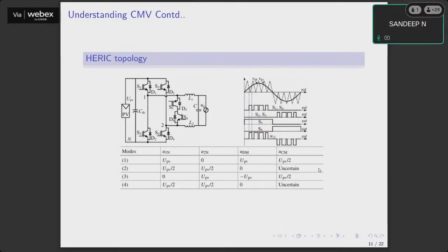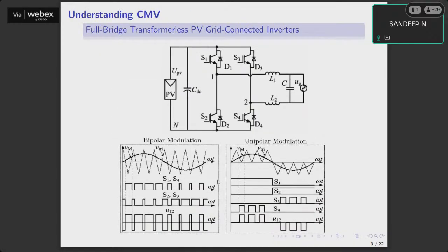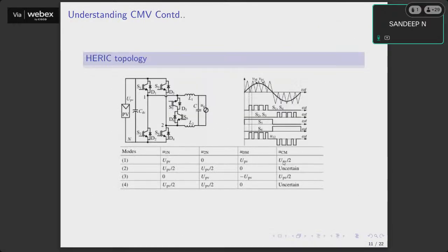So out of these two, unipolar and bipolar, unipolar is better because harmonics are less. The moment harmonics are less, the filtering is going to reduce significantly. So keeping that in mind, people started using unipolar. But the problem is that with unipolar, the common mode voltage performance is going to deteriorate. So how to tackle that? In order to answer that question, I want a unipolar output at the inverter terminals, and I also want to reduce the common mode voltage. That is where the topological play started.